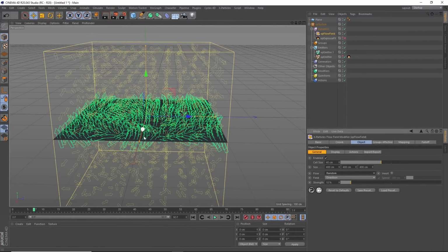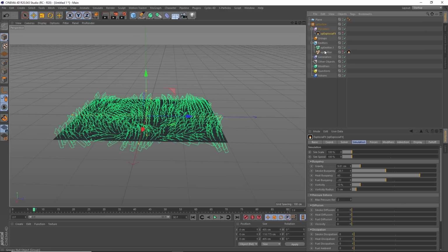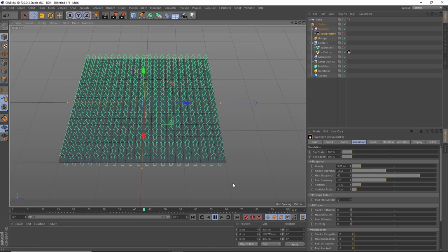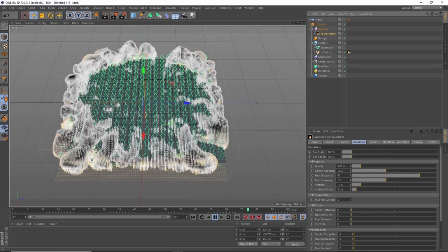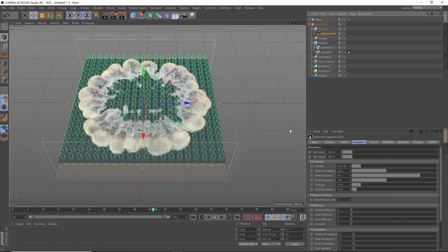So we can change stuck particles' orientations using dynamic objects. Let's just delete that flow field. Instead, what we want to do is use our ExplosiaFX shockwave. If I hit play, nothing happens. Our shockwave is calculating, but it's not doing anything to these particles. So what do we have to do?